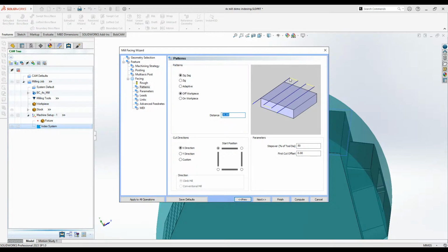I believe it's a quarter of the tool, so it'll be a quarter of 2 inches, or a half inch off of the tool, move over, and then move back over off of the tool for the next pass.